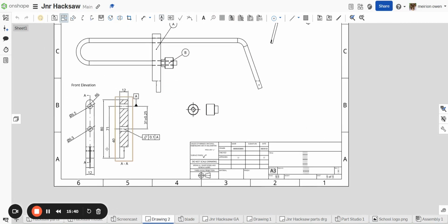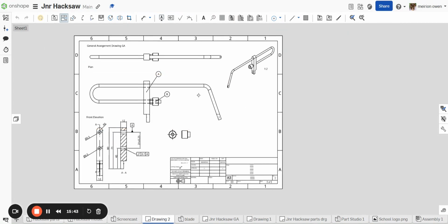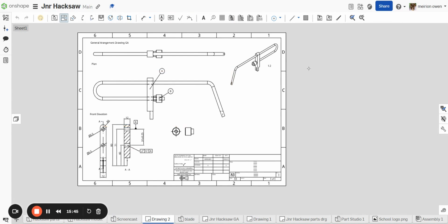In that case, do what I did in the first set of drawings. So, you've got to make sure you put sufficient information on there that somebody else could manufacture it. It might go over 2 pages. You might have your general arrangement on a separate drawing and a parts drawing on a separate one. You've got to think about how it works, right? But try and keep the scale 1:1 if you can. It's okay in your isometric drawings, I guess. There you are, and that's it. So have a go and see how you get on.